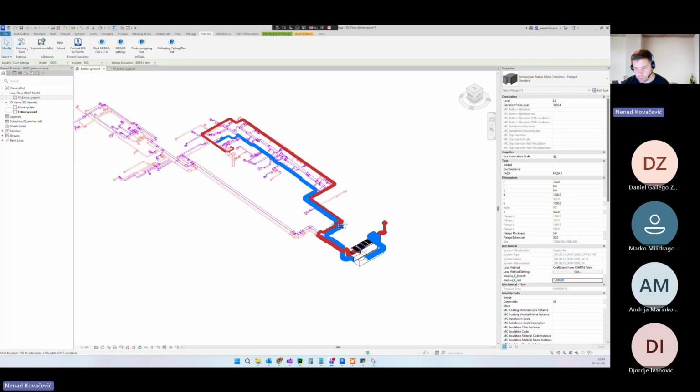We have a situation where we have two phases of ductwork. With two or more phases, I think that is a Revit issue, when you have some part of the network in one phase and some part of the network in the other phase. I know that in that kind of situation, Revit will just declare some phase to have an airflow of 0. That is something which we didn't foresee. But I did write it down. I will see what we can do over here.